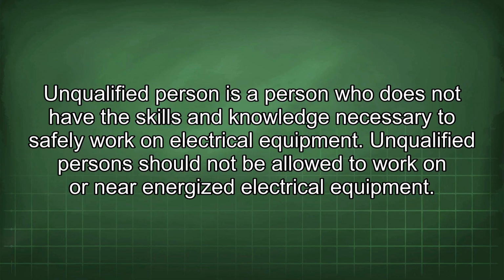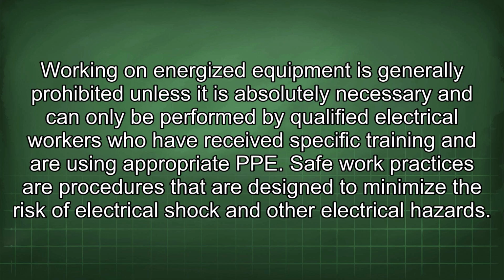An unqualified person is a person who does not have the skills and knowledge necessary to safely work on electrical equipment. An unqualified person should not be allowed to work on or near energized electrical equipment. Working on energized equipment is generally prohibited unless it is absolutely necessary and can only be performed by qualified electrical workers who have received specific training and are using appropriate PPE.